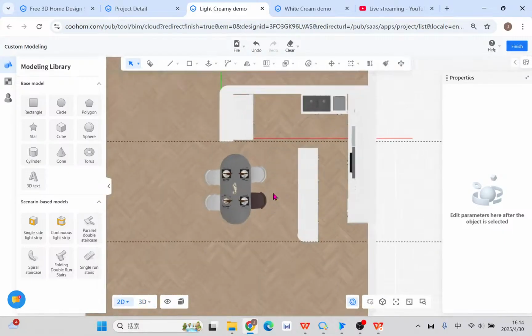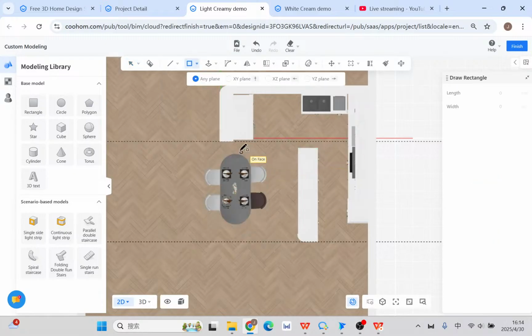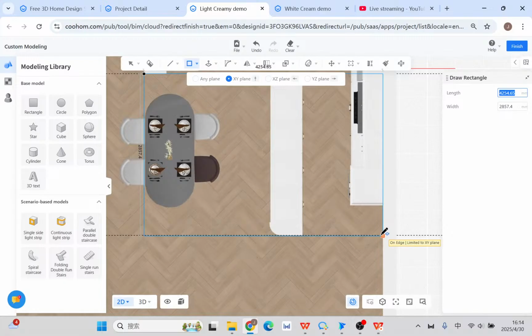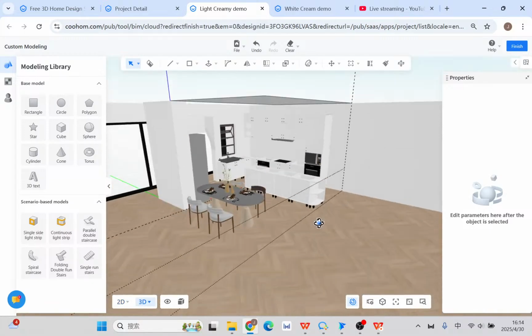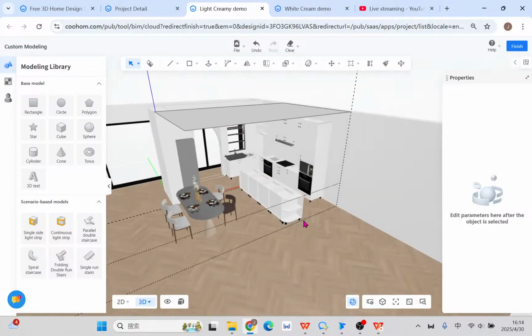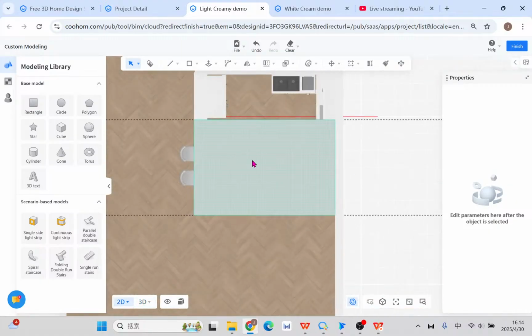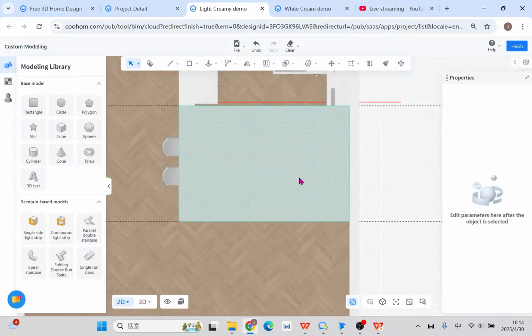Now we can directly turn to 2D using rectangle. The drawing is easy. First, click the starting point and then the end point. It's better to control with the XY panel, and then mark out. For example, here, this is on the edge. Check with 3D to see. Yes, it is fine, right? It's on the top, but it's okay because we already have some of the basic ceiling extrusion. Maybe at first you can't see it, but later just pay attention here.